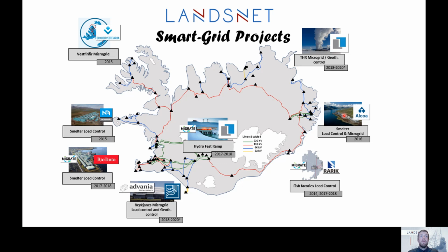And usually for those schemes today, we have implemented 2 steps of load increase and 2 steps of load decrease, on top of any other conventional under frequency protection or something that we had prior to these wide area control projects.